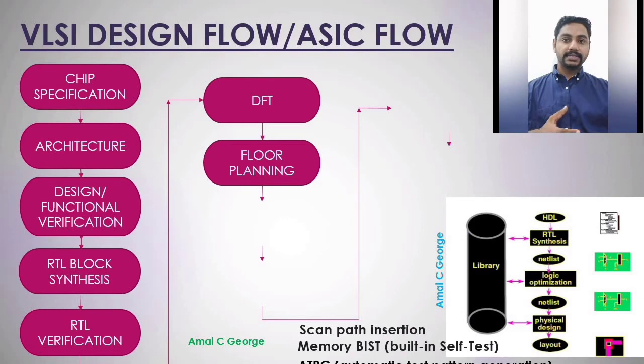So floor planning determines the size of the chip, places the gates, connects them with wires. While connecting, engineers take care of wire length and functionality, which will ensure signals will not interfere with nearby elements. In the end, simulate the final floor plan with post-layout verification process.